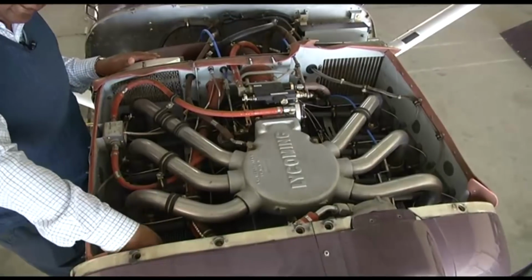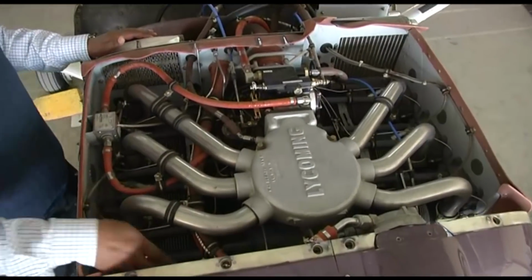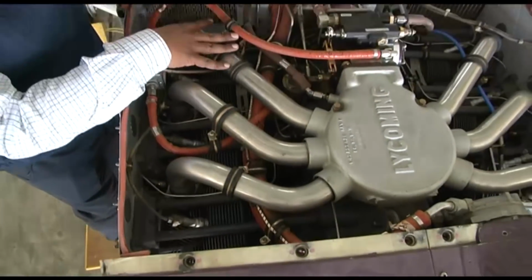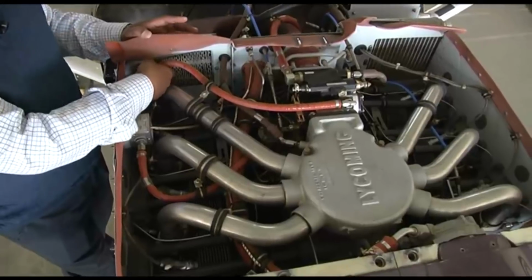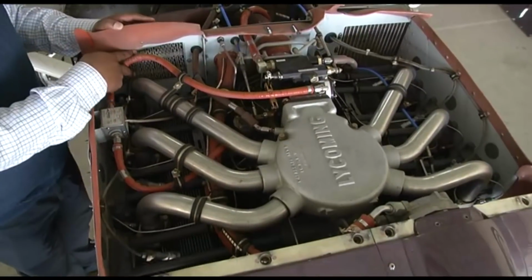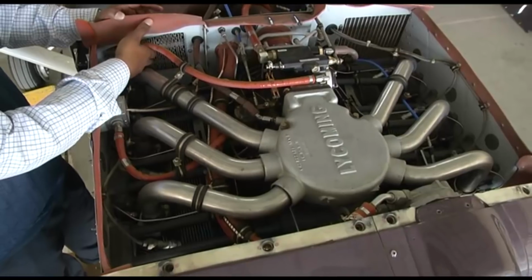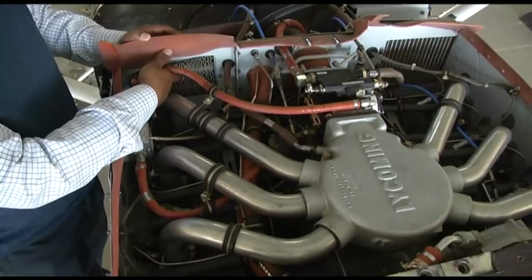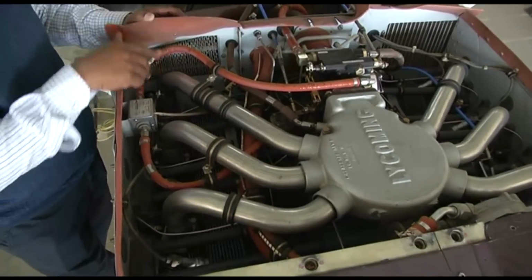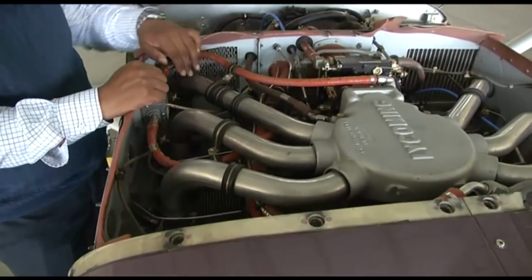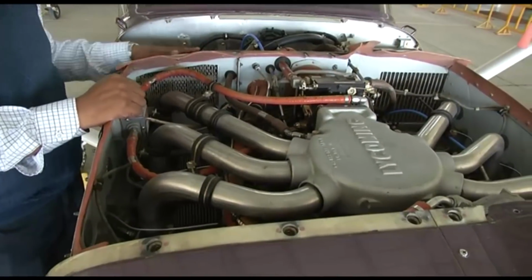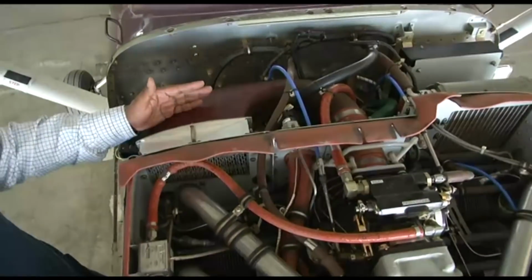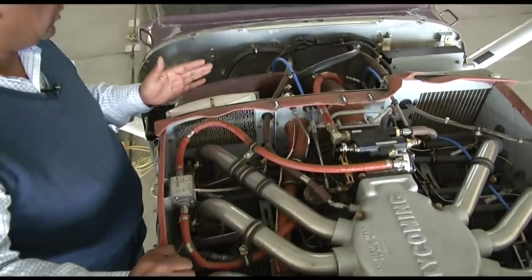So the air enters from this scoop. After the air has entered this inlet, it flows from this side. You can see here, this is an induction air filter. We have read about the different kinds of filters. So this is the filter which is used to filter out dust and other foreign particles from the air. The air is filtered through this and is routed through this duct. You can see here, just aft of the filter there is a duct. The air is routed through this duct.